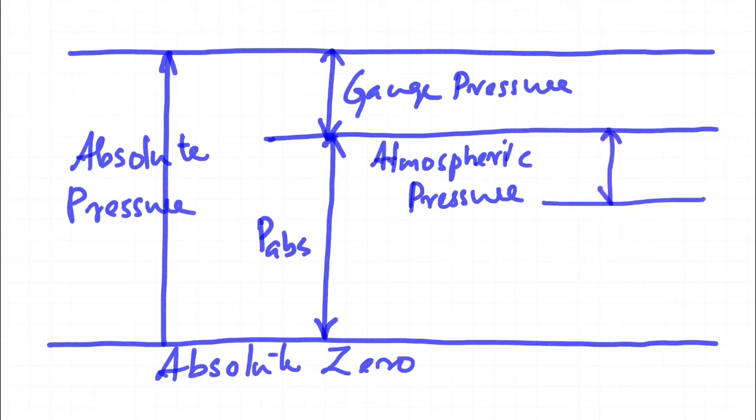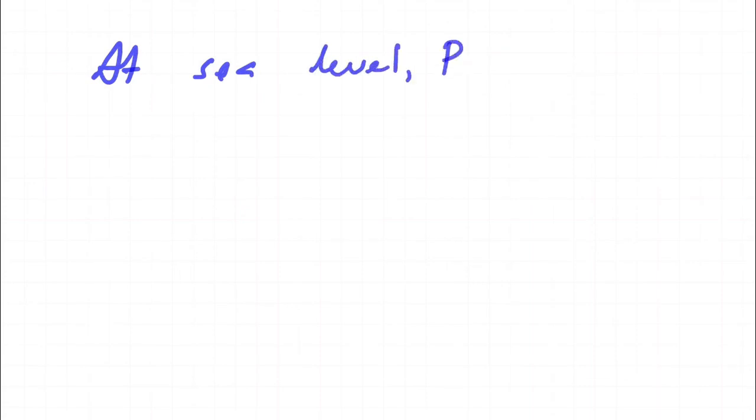Now, suppose we have a pressure below the atmospheric pressure, and you take a measurement from the atmospheric pressure, that too is called a gauge pressure. But because that pressure is below the atmospheric pressure, you can also call it a vacuum pressure, because you feel a negative pressure compared to atmospheric pressure in that condition. So I hope that explained the two terms, absolute and gauge pressure. They're both measured from two datums. One is from absolute zero and one is from atmospheric pressure.